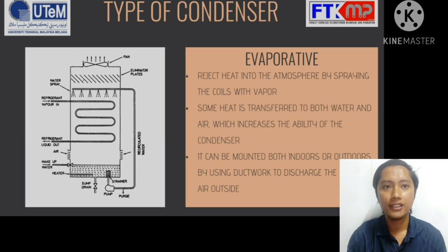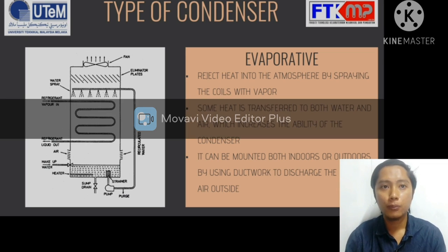For the disadvantages of an evaporative condenser, vacuum maintained is less. Due to less vacuum, work done per kg of steam is less. An evaporative condenser is not suitable for medium and large power plants.